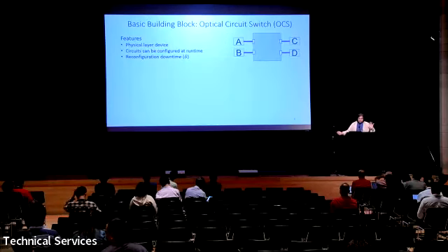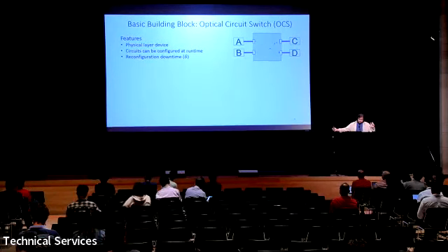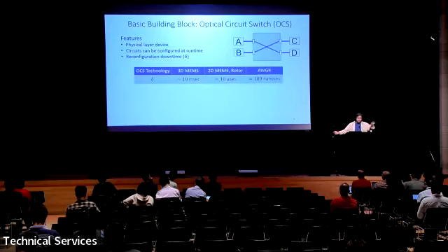I would just give you a very basic background of the optical circuit switch, which is the building block of this direction. Optical switches are layer 1 switches, and they can configure your circuit at runtime like this, which is great. They have some amount of reconfiguration downtime, which varies from milliseconds to hundreds of nanoseconds based on your actual optical switch hardware.